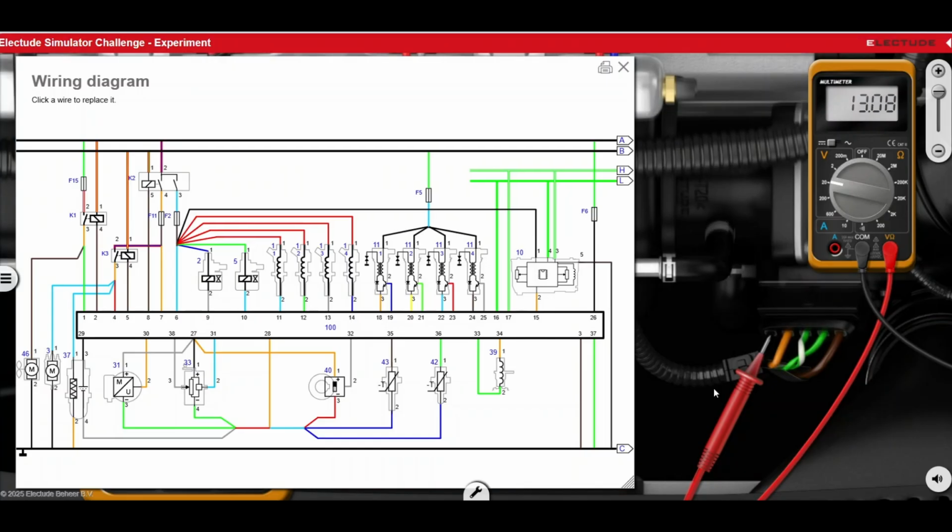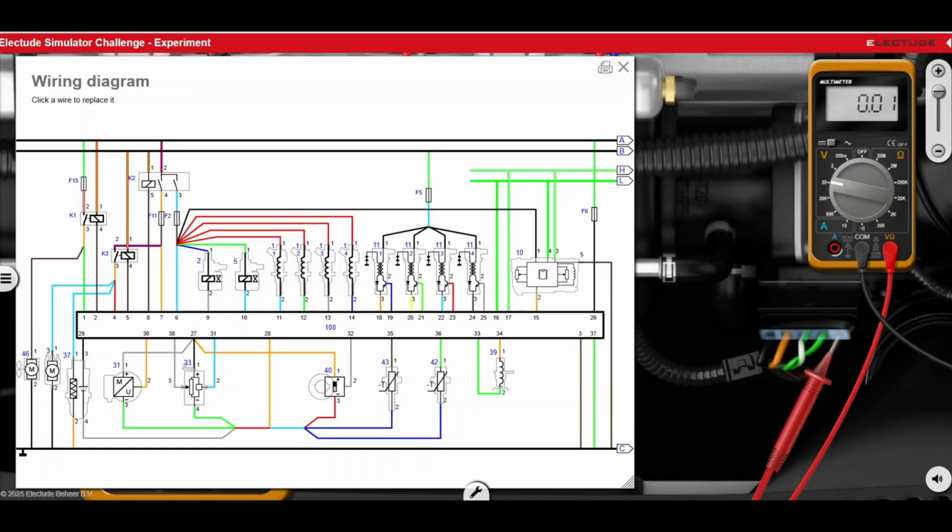Looks dark brown. Okay. Come here, 0 volts, and also if you move the multimeter to resistance, you can hear you have continuity and you have only 4.6 ohms. So let's go back to voltage. That is our ground. We proved it.